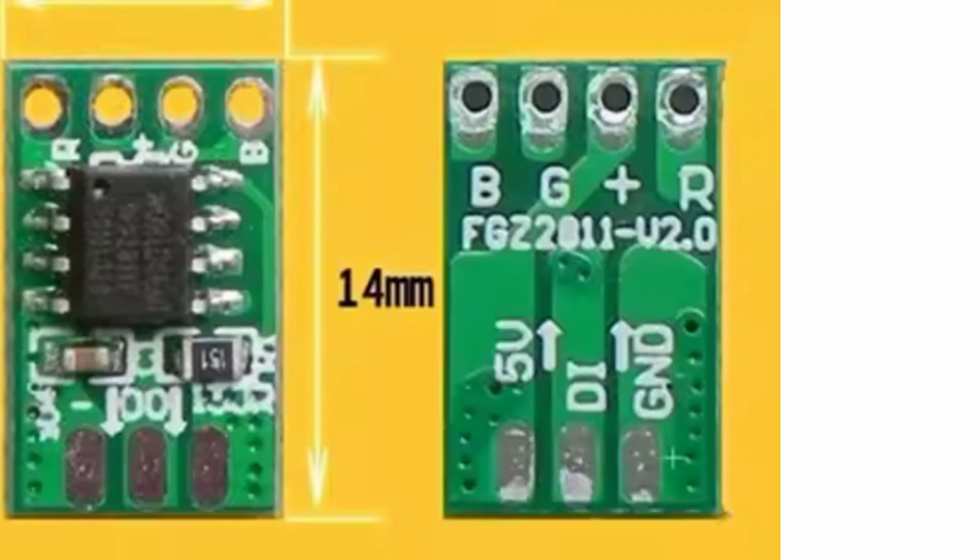And at the bottom there's 4 connections as well, but it's a wee bit sneaky. On one side there's 5 volts, and the other side there's ground. And those have got a load of vias on them each, so they're stapled through from both sides of the board. The 5 volts is the 5 volts, and on both sides of the board the ground is the ground. But on one side of the board it's DI for data in, and on the other side of the board it's DO for data out. So that's how you daisy chain them.